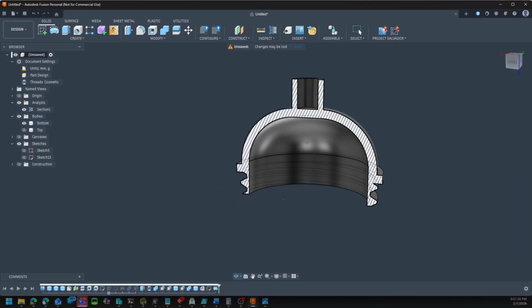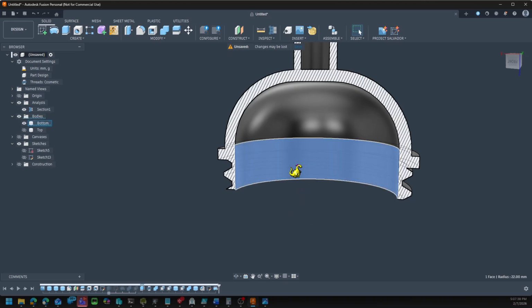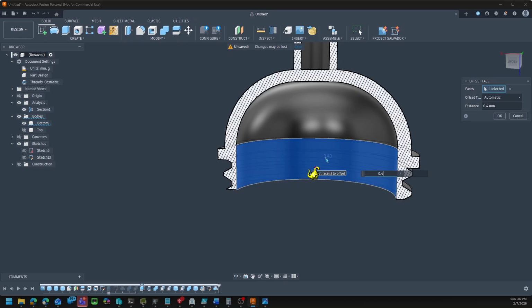That's just a 0.4 millimeter nozzle. That's going to be 2 walls right next to each other, and we'd like to have 3. I need to make this interface a little bigger. Okay. Click on this interface and hit my push-pull tool, that's Q. Let's bring that out to give us just another wall, 0.4.